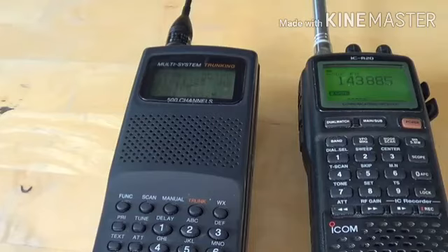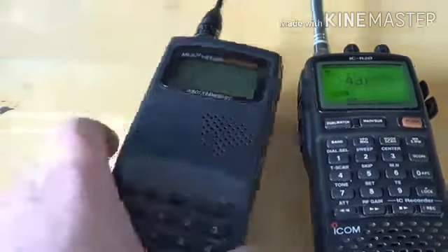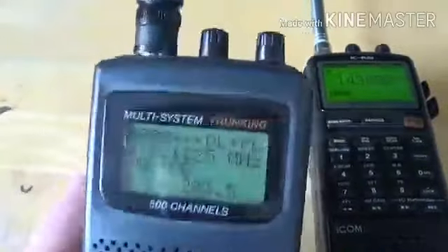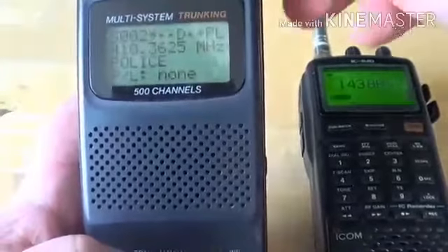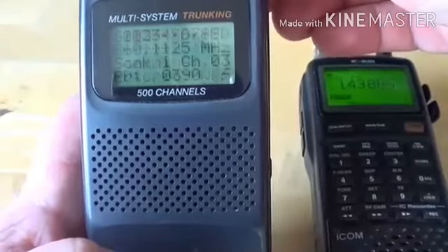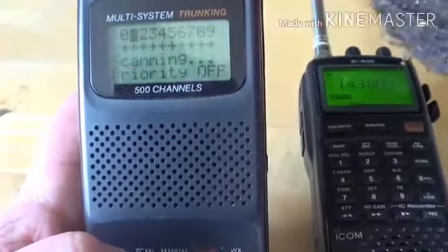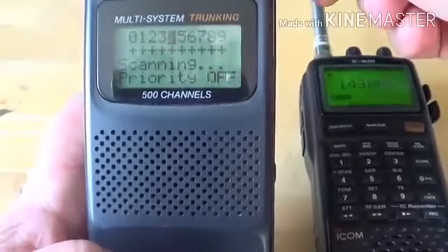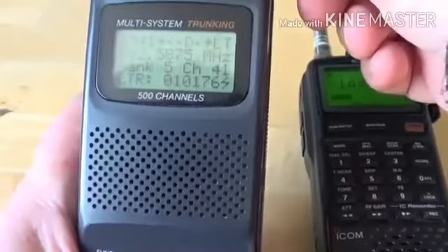By putting it just at the threshold, in that little line between where there's static and there's no static, you know that in general, if you're scanning for signals, even the weak signals will be able to be heard through the squelch. And that's very important, because when you scan with a scanner or radio scanner, you just want to make sure that you don't miss out on any signals. So by setting it at a very low setting, you know that even if the signal is not very strong, you're still going to hear everything that's happening.